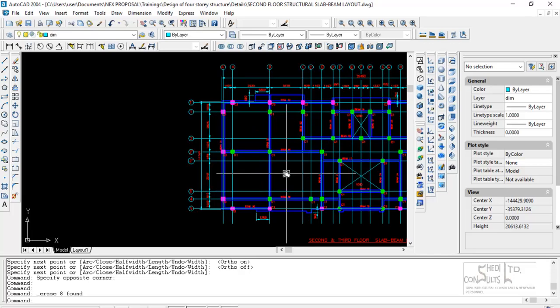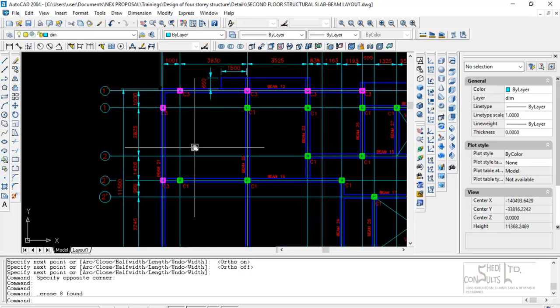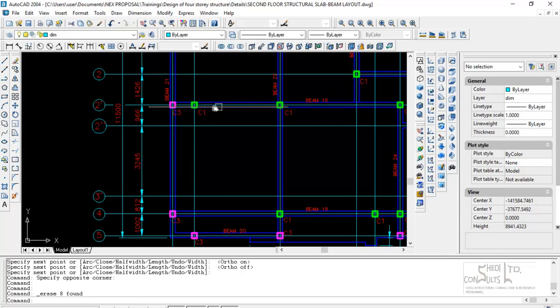So when you have slab panels, two-way, one-way, and you want to give them mark numbers, the guiding principle is that the slab panels are similar: the planned dimensions of the slab panel are similar, and the continuity of the edges is similar. Remember, if the edge is continuous on that side, that side, that side, as in this case, for example, continuous on 3 sides and discontinuous on 1 side, the yield line failure mechanism is such that you will have more load onto the edges that are continuous as against the edge that is discontinuous. This is the requirement of the code of practice, BS 8110.